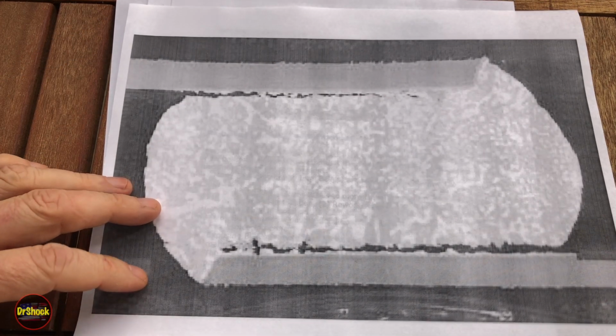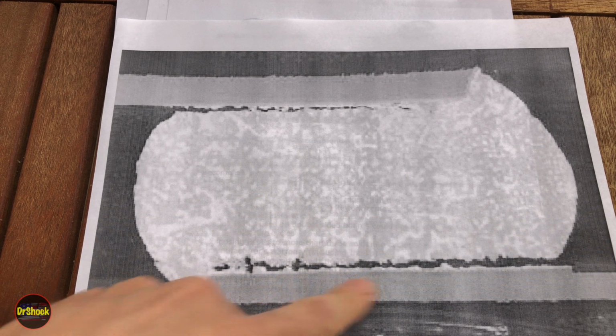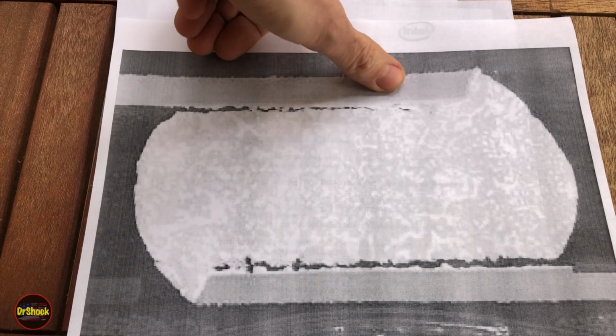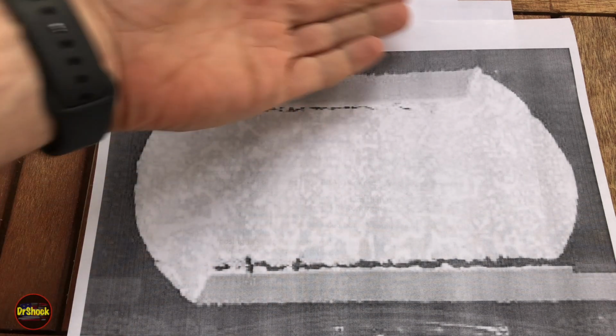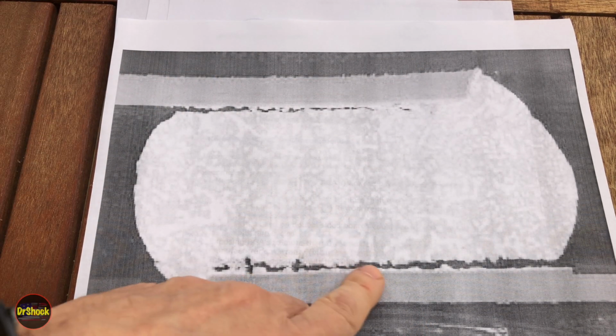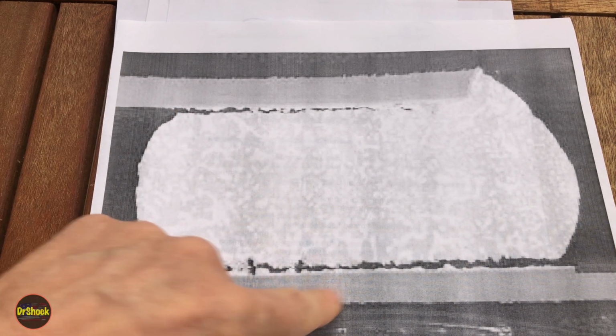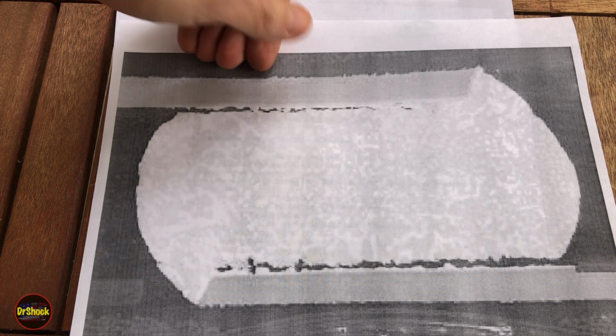Now guys, I thought it would also be good to show you a little blow up. This is a microscopic view of a solder ball underneath a BGA part. Here's part of the pad on the bottom substrate. Here's the pad on the device. This is looking out towards an edge. And what you can see is they've kind of cut this in half, and you can see microscopically these cracks that can form through thermal stress over time, at both the pad on the device and the pad on the substrate.